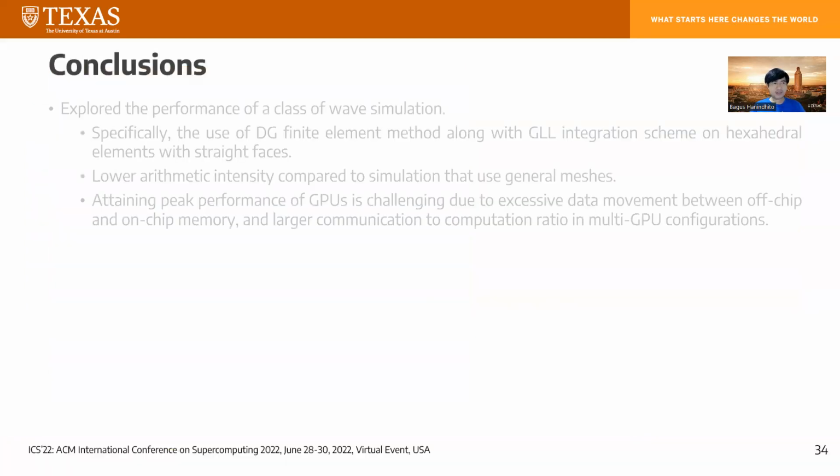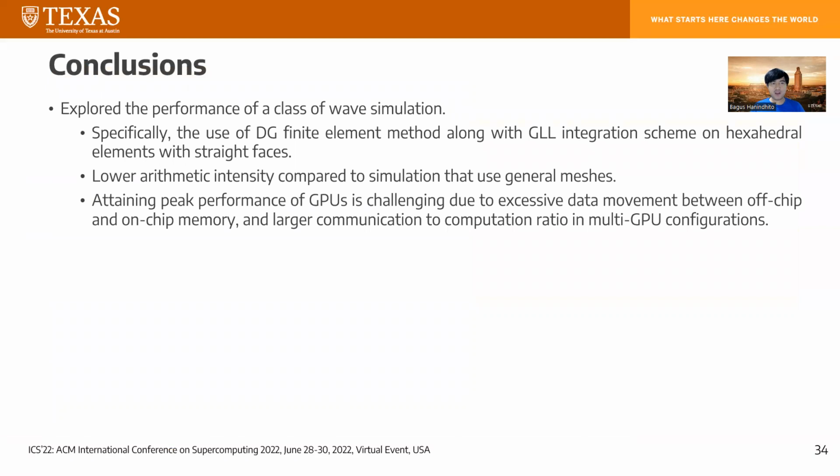So the conclusions: we explored the performance of a class of wave simulations. Specifically, what is unique in our work is the use of discontinuous Galerkin finite element methods along with GLL integration schemes on hexahedral elements with straight faces. It has lower arithmetic intensity compared to simulations that use general meshes. This way, it is very hard to attain peak performance of GPUs because of the excessive data movement and very little computation to overlap with communication.